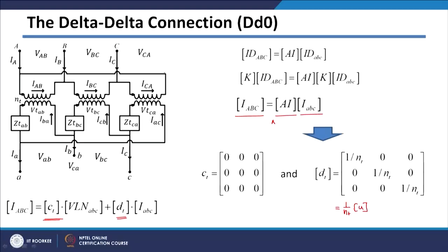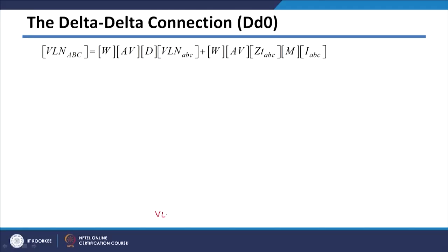So, we have got A, B, C, D parameters, and as I told you, we are also interested in calculating capital A and capital B parameters, and those capital A and B parameters we need in this format. So, we need V_LN small abc, which is secondary side voltage, written in terms of primary side voltage, which is V_LN capital ABC minus your B_T parameter into secondary side current I_abc. So, we want the expression to be in this format to get capital A_T and capital B_T parameters.